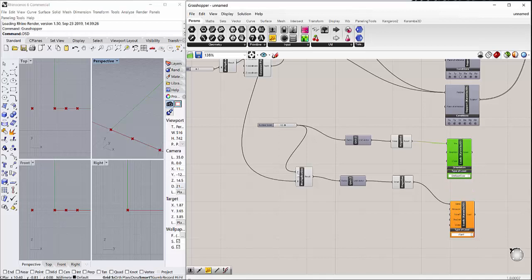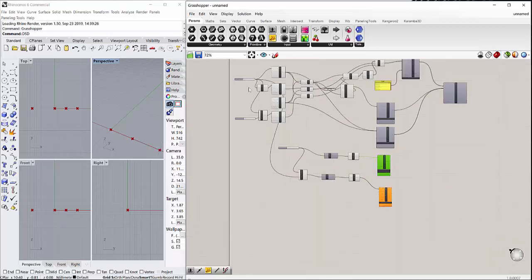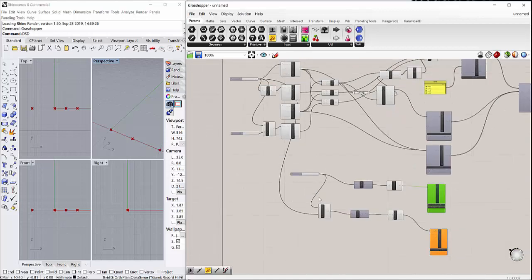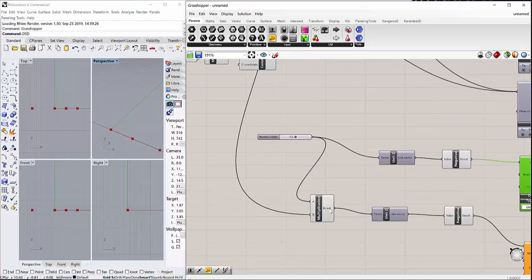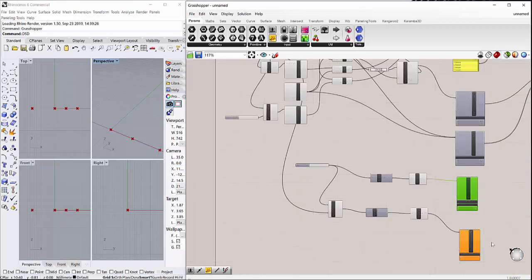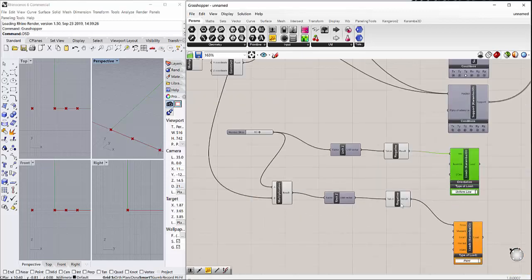So it will be multiplied by 5 because here it is 10 and here is 0.5, which when you multiply is 5, and the value for this force will be 5. And it is a negative, so this will be -5. So now I created a uniform line load and a point load.